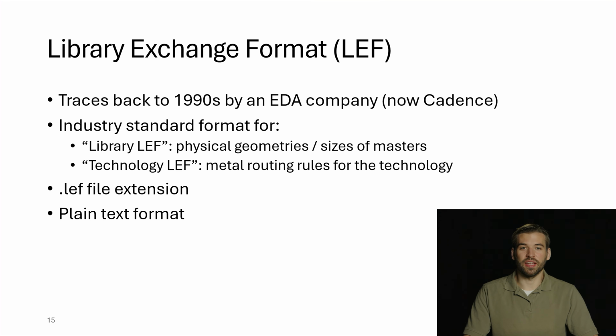Next, we're going to look at the Library Exchange Format, or LEF. It was created in the early 1990s, possibly late 80s actually, by a company that eventually became part of Cadence. Similarly here, LEF, along with DEF, became the industry standard format for physical information in circuits. It's been updated since then, and it's still the de facto standard.